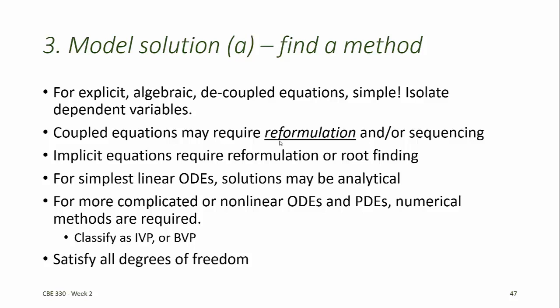Implicit model equations need to either be reformulated or they will require a root finding method. For the simplest linear ordinary differential equations, solutions may be analytical, and it may be that you can find them using the dsolve function in MATLAB, for example. For more complicated or nonlinear ordinary differential equations and partial differential equations, often numerical methods are required.